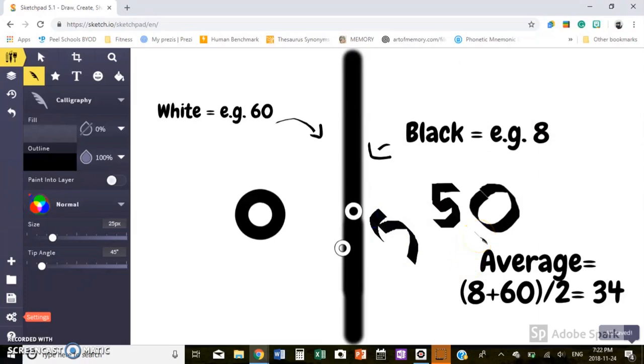And how much of a correction is made is multiplied by the KP value. So assuming that the KP value is 1, it's subtracting and adding exactly 26. But if you make it 0.5, for example, it makes that correction by only 13. And that's essentially how it works.